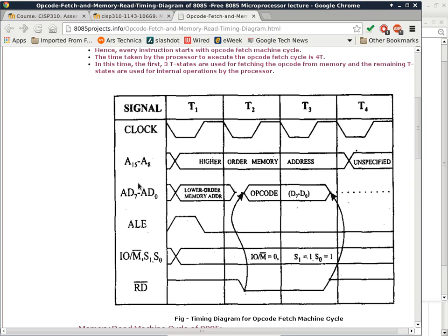Okay, so anyway, getting back to the circuit board thing, the number of layers has to do with the thickness. The simplest kind of circuit board only has traces on one side of the circuit board. They're simply called single-sided PCBs. So on one side you will see copper traces, and that's the only part that can conduct electricity. And then you can have double-sided circuit boards, right? One on the top and one on the bottom. That's pretty easy. I mean, nothing tricky to it.